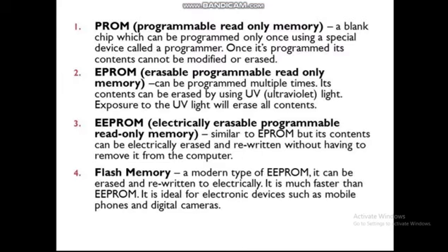Now coming to different types of programmable read-only memory. The user can write a program, data or any kind of information permanently into a PROM, that is programmable read-only memory. Because PROMs are only once programmable, the user can write his program or data into a PROM only once, and it needs special equipment called a PROM programmer for writing the programs into PROM. It is found in almost standard processor kits, and a universal PROM programmer is also available, which is more powerful, provides greater facilities and accepts varieties of PROMs.